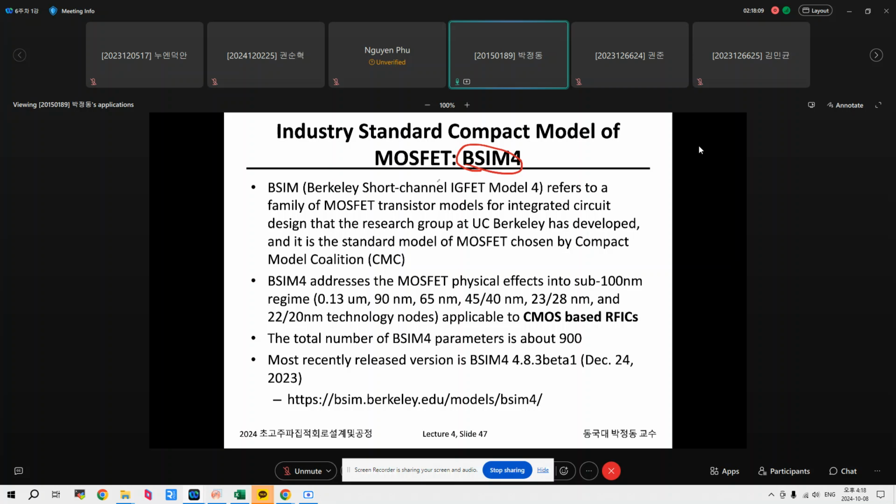You notice that insulated gate is the true name of MOS, because in modern technology we don't use oxide. So we should not actually say MOS. Exactly speaking, this is an insulated gate FET, so IGFET is the correct name. Anyway, BSIM means this.